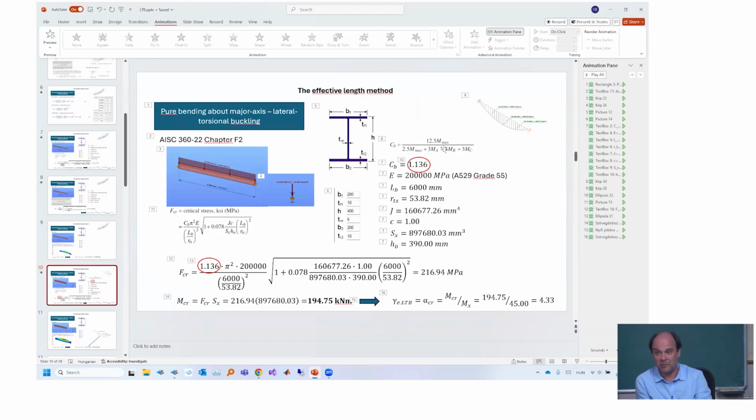It should better speak about stresses at certain positions. So if I have a non-uniform cross-section, of course, the stress distribution will be different. That's the reason why we use tapered columns to somehow equilibrate the stresses along the member. So if the tapering is well done, then we can have maybe constant stress on the compression flange. So these CB factors are really for uniform members.